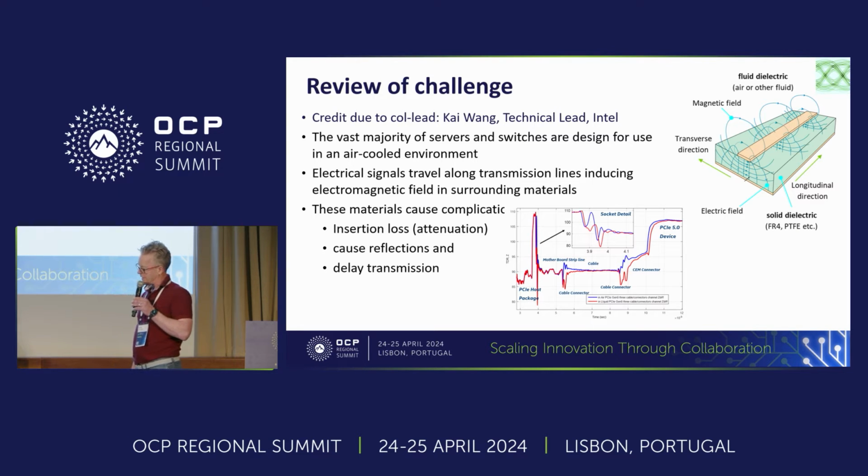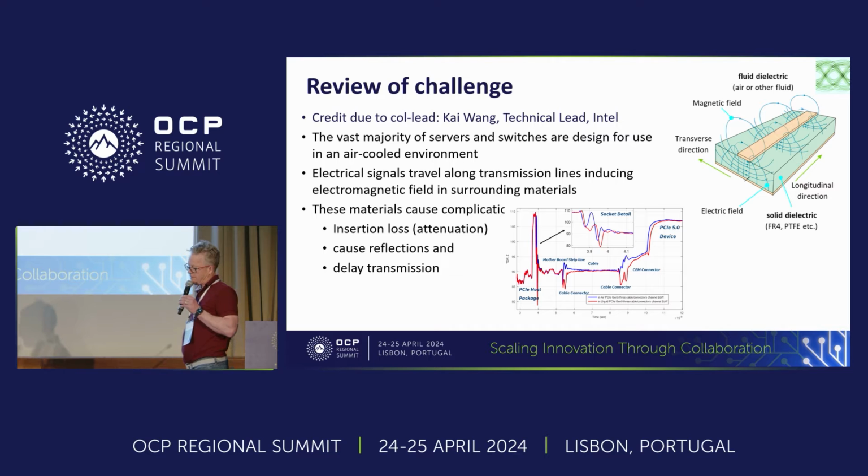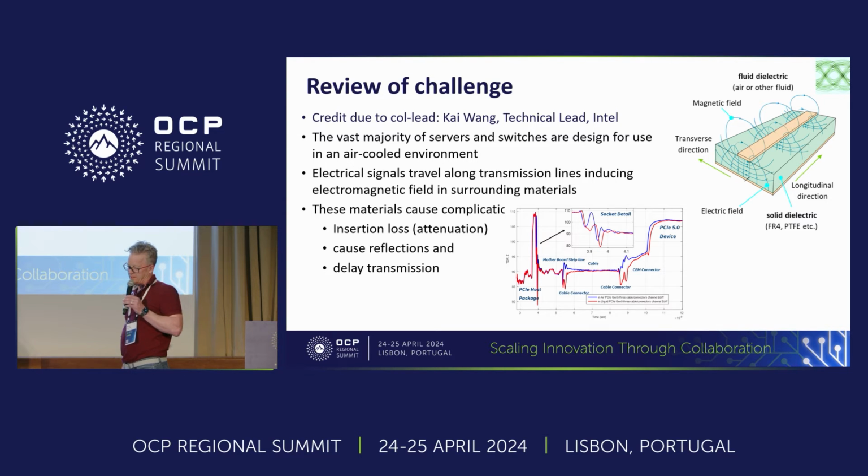And this becomes more and more apparent as we have higher data rates and a greater range of equipment in the immersed environment. So as you probably know, as electrical signals travel along transmission lines or conductors, you don't have the transmission of information directly on those lines. It's a field around that line which is generated that causes the information to flow. And those fields, as you can see in the image on the top right, they interact and are impeded in part by the material that is on the top and bottom side. As you can see here, we have a solid dielectric underneath the transmission line. On the top, we would have air. If you replace the material on the top of the transmission line with a liquid, it's going to store and dissipate energy and slow down, distort, reflect, and delay the information.